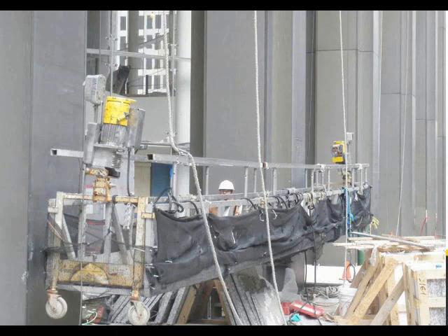Ironically, many of the ropes commonly used in conventional fall protection are not ropes that meet the life safety rope standards that we've mentioned previously. Historically, these tend to be laid ropes, often polyester, and of a 5/8 inch diameter. In the old days, it took a 5/8 inch rope to get up to OSHA's 5,000-pound strength requirement, so that was part of the deal there. Nowadays, with modern technology, 11 mil and 1/2 inch ropes are becoming more familiar.